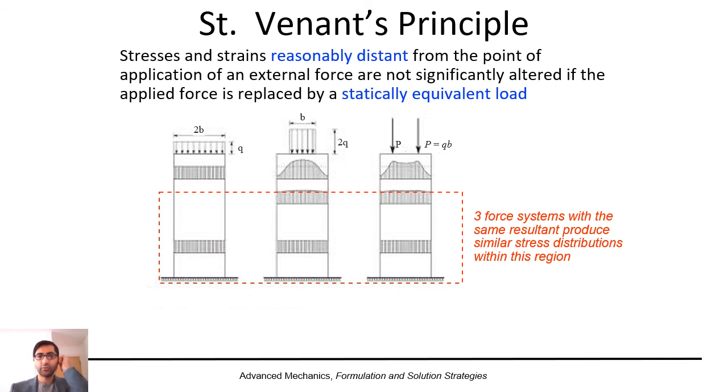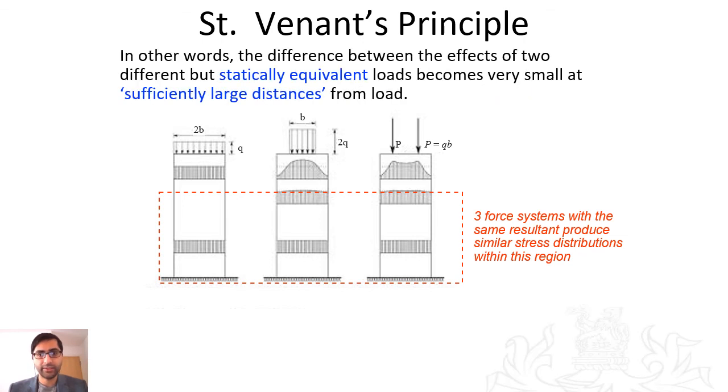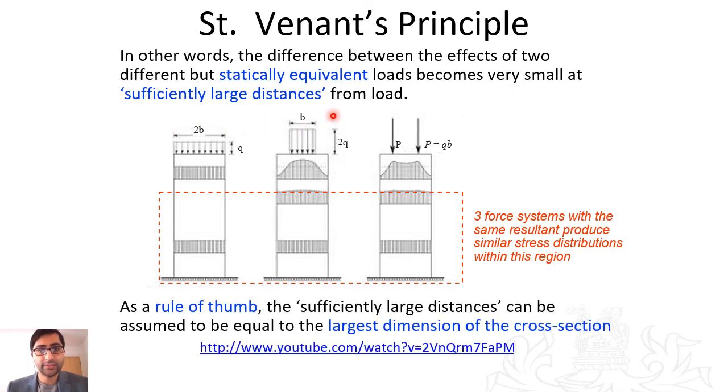That's basically Saint-Venant's principle, and the compatibility constraints are kind of related to that. We don't go into details, but basically, in other words, the difference between the effect of two different but statically equivalent loads becomes very small at sufficiently large distance from the load.